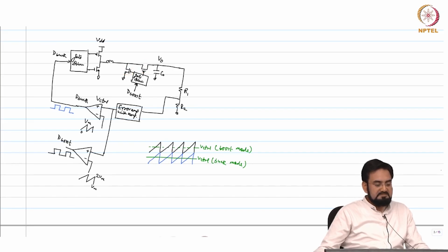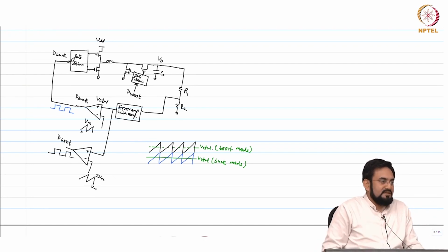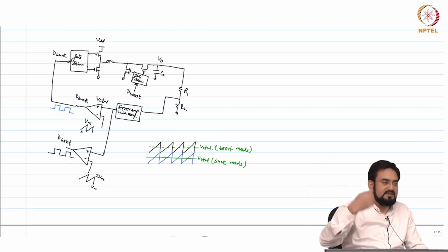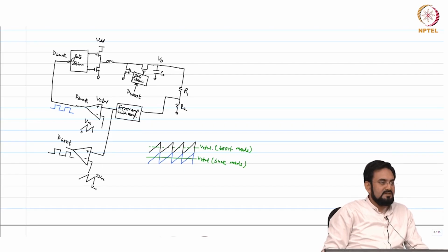Okay. So if you don't have any limits on the duty cycle, it will very smoothly go from buck mode to boost mode. There is no buck boost mode as such here. Okay. There is no condition where all the 4 switches will be operating, because your maximum limit is here 100% and your minimum duty cycle in case of boost is 0%.